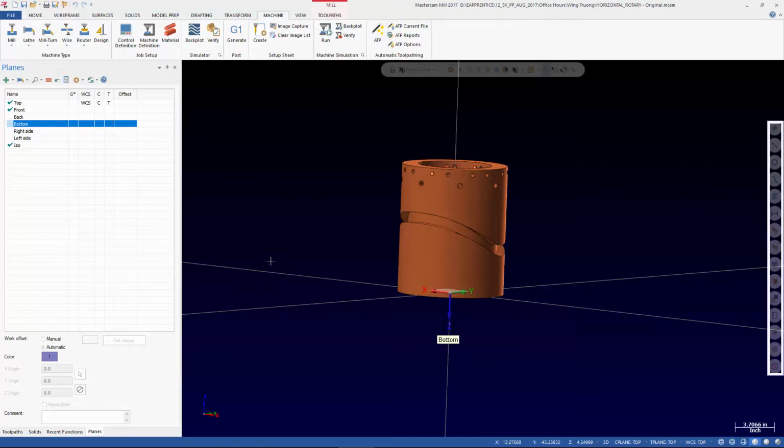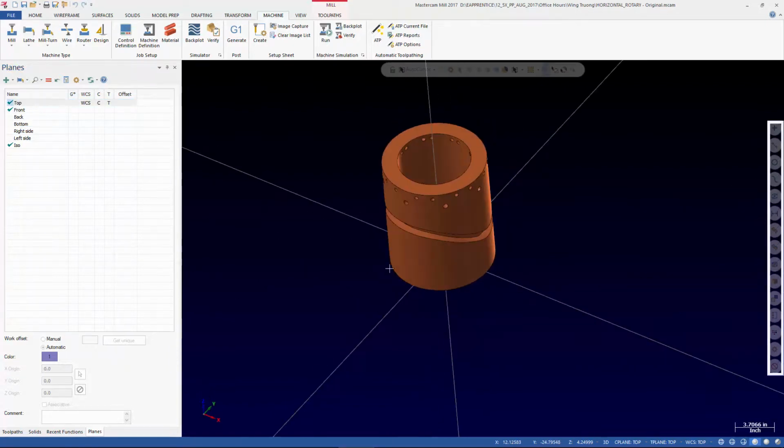And this is a problem that happens when we start programming for a 4th-axis vertical machine. Because what that means is that when we start with top and we're rotating about X, I can now program with front and X stays pointed to the right. But when I pick bottom, X positive flips. So I can't use bottom for A180 with the stock post. It gives me an error. And the same thing happens with back. I can't use this for A270 if I'm programming a vertical machine. It also gives me an error.